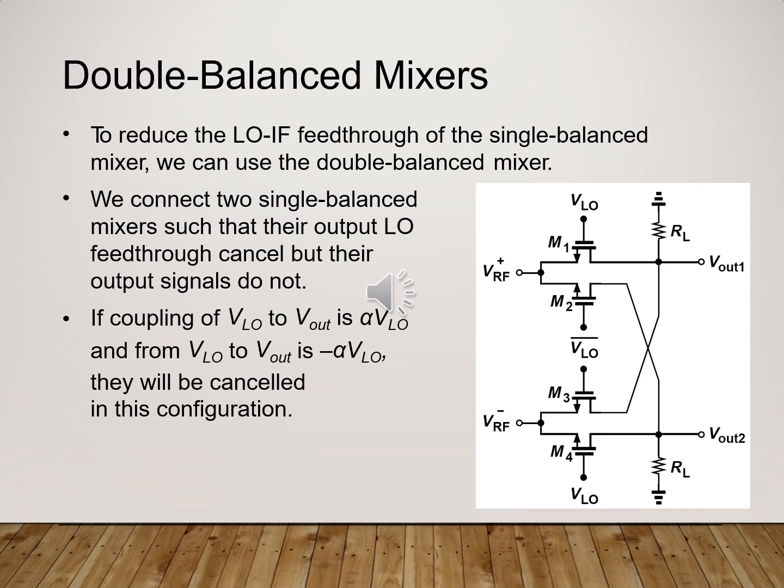So, as an advantage of double balanced mixers, both local oscillator and RF are balanced, providing both local and RF rejection at the intermediate frequency output. All ports of the mixer are inherently isolated from each other. Also, it has increased linearity compared to the single balanced mixer. Also, it has improved suppression of spurious products such as intermodulation of the mixer.